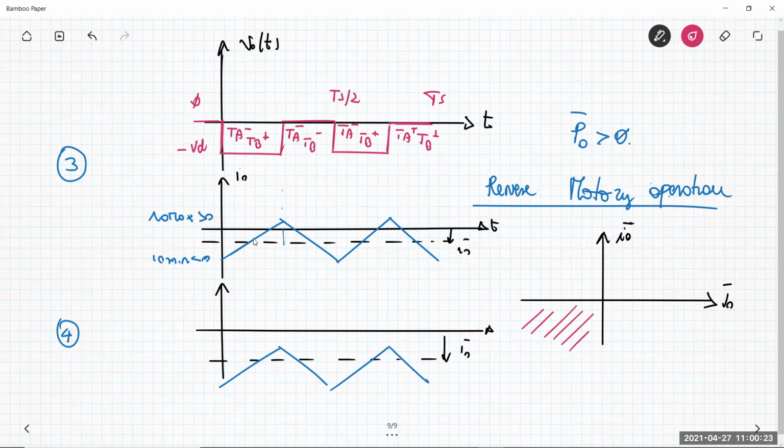Students maybe remember that in DC-DC converters that are not bidirectional, like the buck or the boost, the operating condition can be divided further into continuous conduction mode and discontinuous conduction mode. In continuous conduction mode, the current through the load was always positive, and the current through the load is null when you go into the discontinuous conduction mode.